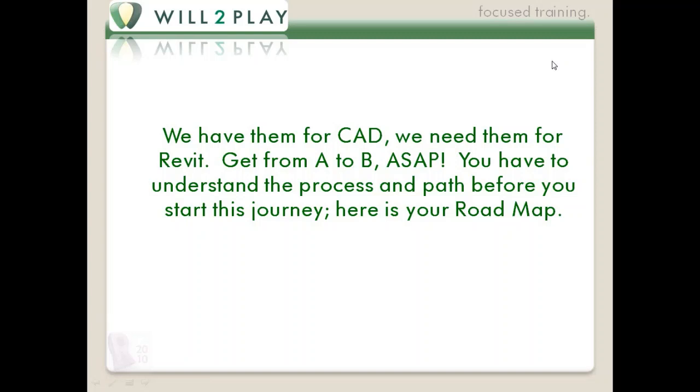Really, very important. I'm going to give you some best practices, talk about how AutoCAD and your AutoCAD to Revit drawing problems. If you take your AutoCAD title block, flip it into Revit, you're going to have some problems. Talk about scale, line type, lots and lots of things. Okay, labels and text and lines.